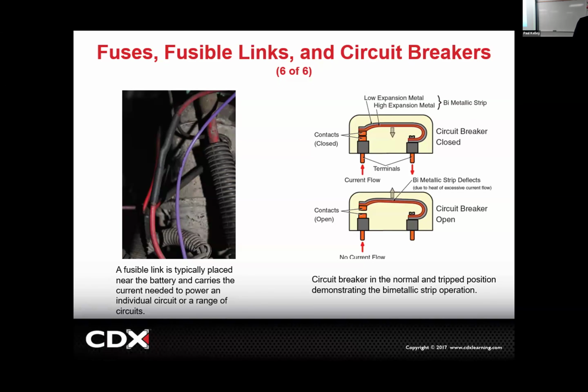And then that resetting circuit breaker, this is a shot of that. You can see it's two pieces of metal. When they get hot, it'll separate. You notice there's an open contact now. No power for your windows or whatever. But then when it cools, it relaxes back down and touches. Now your windows work. It'll just reset itself. It's pretty nice. You can pull the fusible link while it's still on there to see if it's... Yes, that's exactly what I would do. If it burned up the copper inside, it'll just be like...